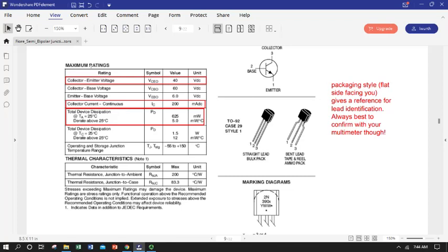This is what not to do, in the maximum ratings. So maximum collector emitter voltage. This is that VCEO, 40 volts. Don't put more than 40 volts collector to emitter. So when you look at your supply voltages, your VCC and your VEE, make sure you adjust those so you can't get more than 40 volts, or you could destroy the device or make it behave unpredictably. And you're going to have similar upper limits for collector base and emitter base. So across every one of those junctions, and notice emitter base has a much lower maximum. So be respectful of that.